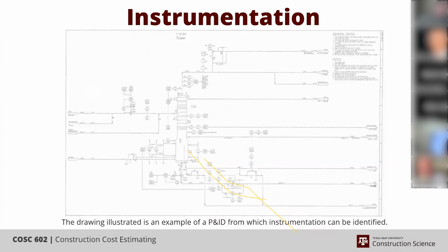And even though the optical cable is more expensive than the wire, 5 optical cables are a lot less expensive than 50 electrical wires. So it cuts down congestion, and it cuts down on cost in your long runs from your process units back to your control room.